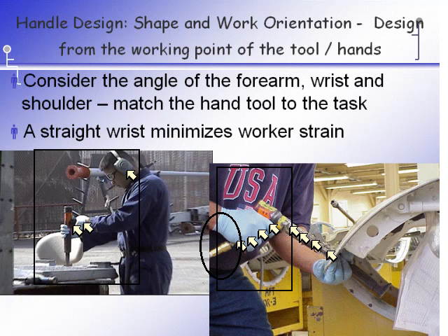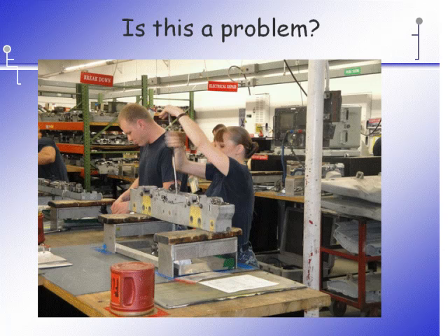It may not, and really the evidence is not very favorable for vibration dampening gloves, actually dampening the amount of vibration transmission into the worker's hands. But gloves can keep the hands warm and dry, and that will help minimize the contributing factors. So you have to consider here, we're talking about considering where the working point of the hands is and which type of tool you'll be selecting, whether that's more of an inline tool, or a pistol grip tool.